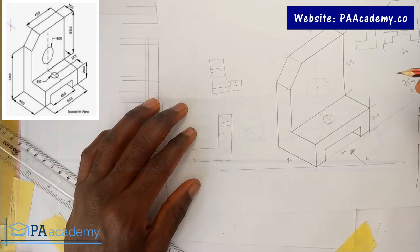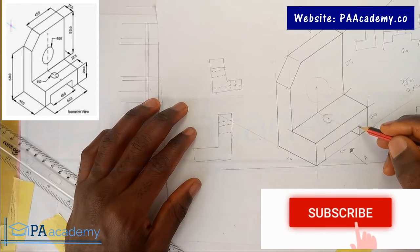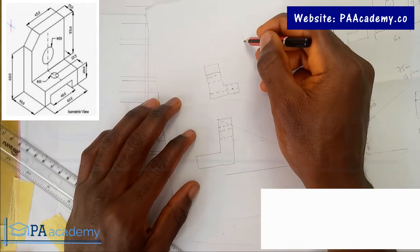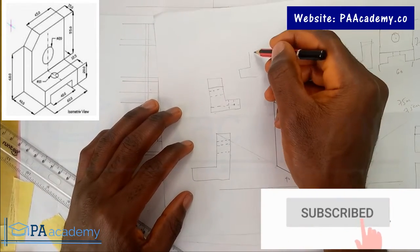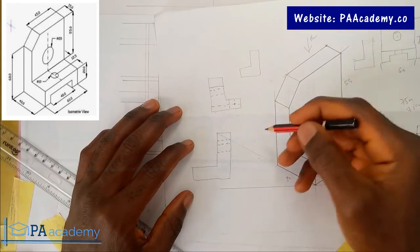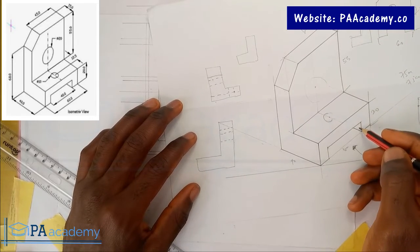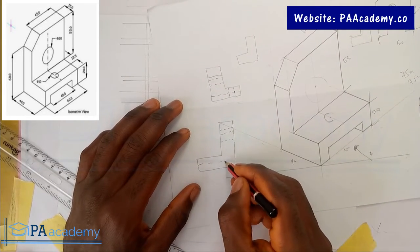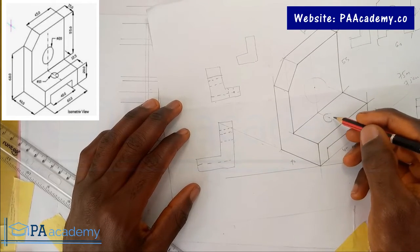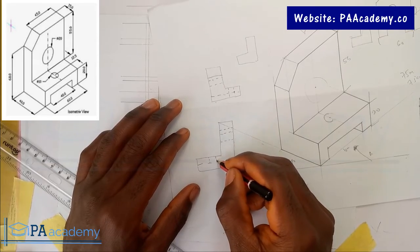So what else? If you look at this part here, this opening here, you can't see it. Definitely what you're just going to be seeing on this side is just a plain surface like this. There's nothing there. So every other thing is just going to be short dashes. All the details are going to be short dashes. So for this opening here, it's going to be short dashes, something like this. And then this other opening for this hole here, you can't see it, so you're going to represent it with short dashes in this manner.